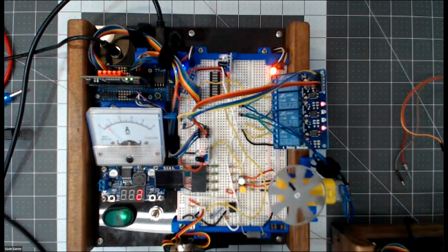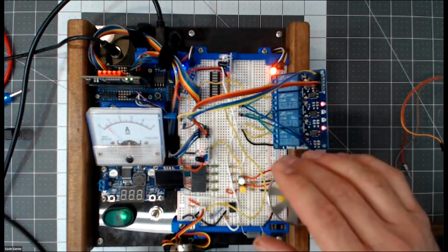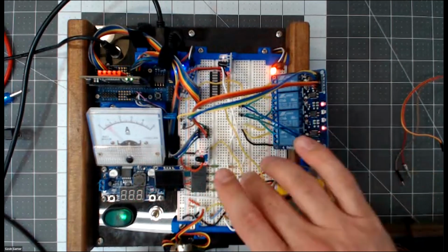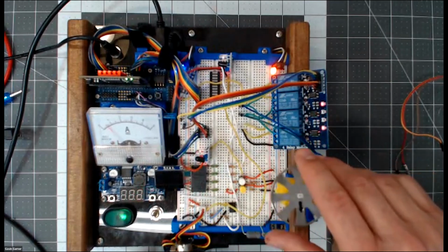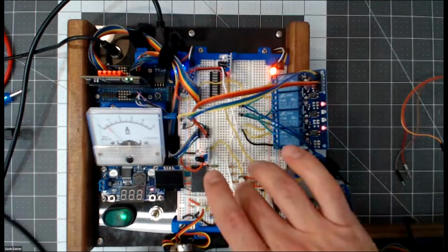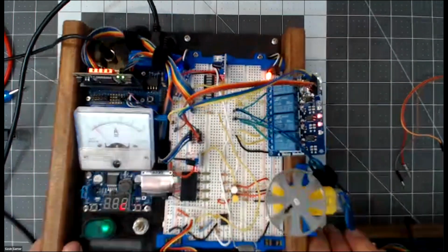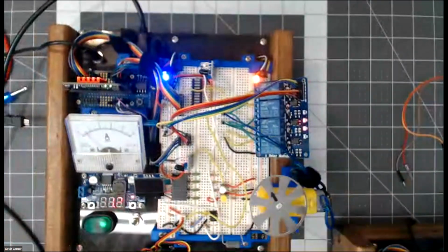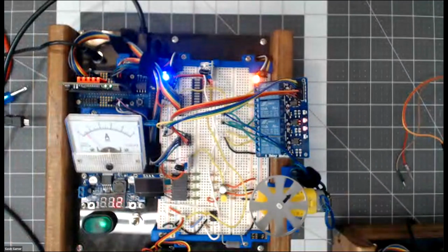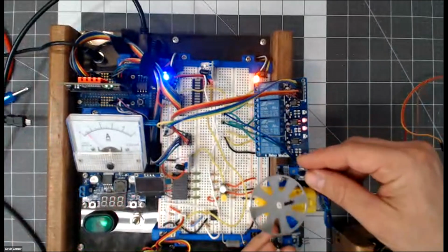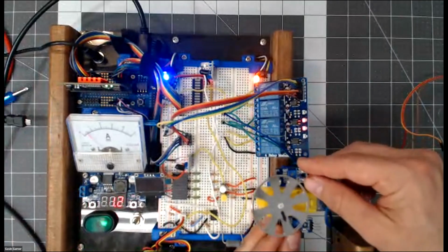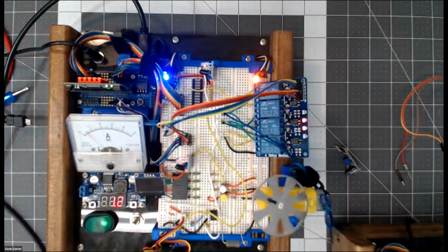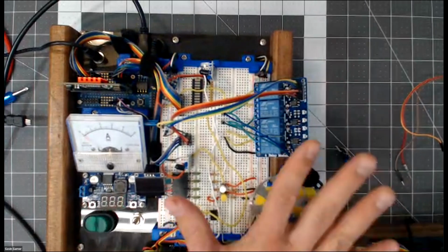I'll mess with this a little bit. So this is setting the threshold. So if it crosses the threshold, it automatically reverses. Okay, so this is just an example of how they're able to make this work with the acrylic disc and the servo system. And again, what they do in the end of the lab was they were using these two IR distance sensors to make a quadrature encoder coming out of this, so they could detect how many positions it's moved through. This is kind of what we'd be doing on these kits.